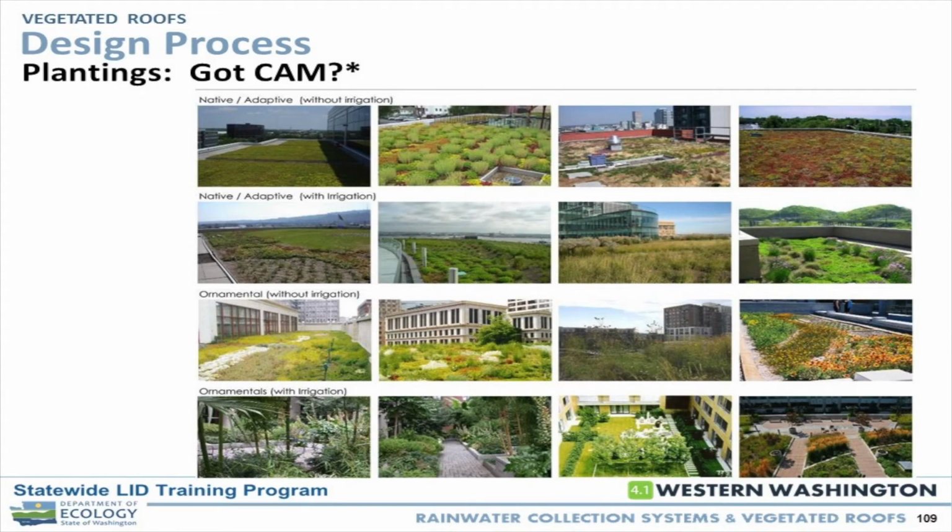Irrigation is another one where people say, potentially, I want to do it without irrigating. This is a discussion that's been happening for 15 years since we started doing green roofs in the Northwest: you can do non-irrigated green roofs. You're going to have significant amounts of dieback. If you have a project where you don't care about aesthetics, it's probably less of an issue. If aesthetics is part of it, then non-irrigated green roofs are probably going to be a little less satisfying for your clients.